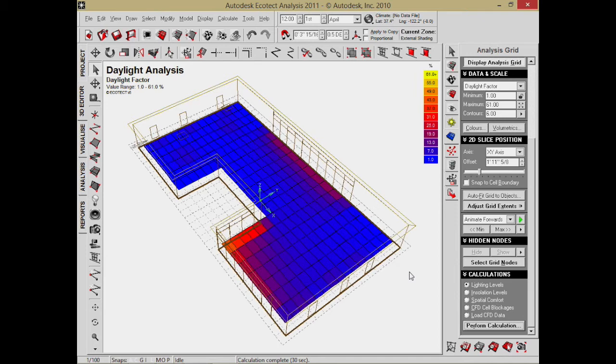Okay, just an average. So you'll see we're doing a little bit better over here. Down here in this corner, it's like 37% of the sunlight. Over here it kind of starts tapering off. Here it's like 19 or 20%. Let's take a look at this. I'm going to reduce the scale again a little bit. Make the top of the scale say 40, just so it's a little more intense, or 30, something like that. Again, if I want to show the contours, I can.